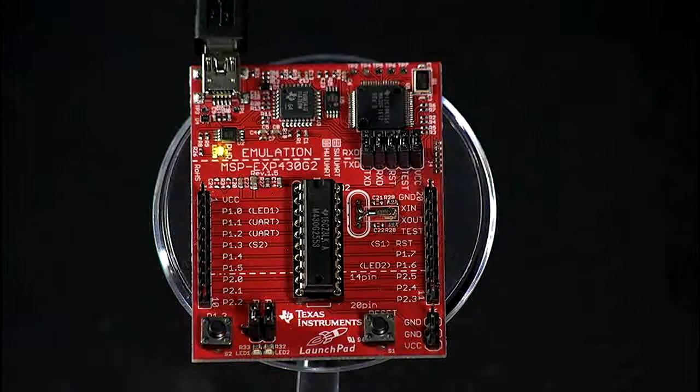So the procedure to solder the crystal oscillator to the LaunchPad is there in step 1. Go ahead and solder the included clock crystal to the LaunchPad board. The crystal leads provide the orientation. They're already bent down in such a way that only one position mates it up for the soldering. Be careful not to bridge the pads.